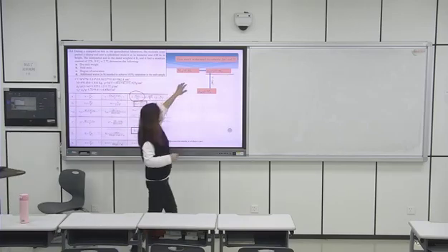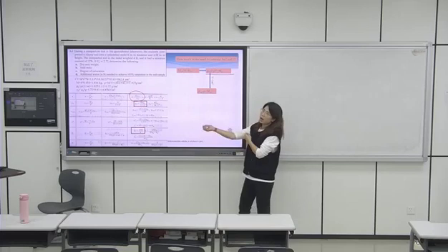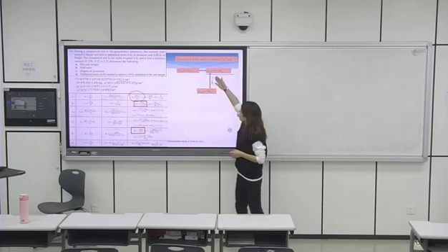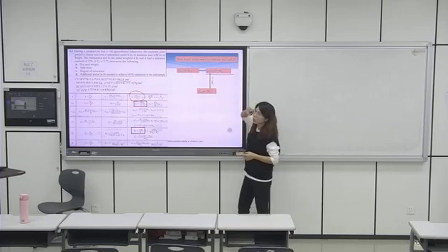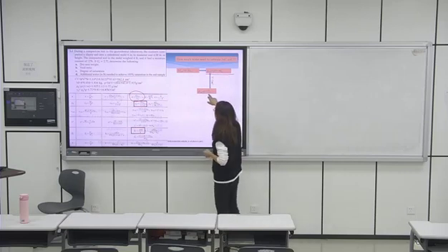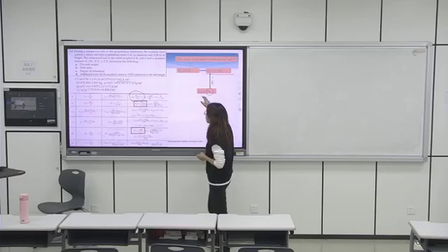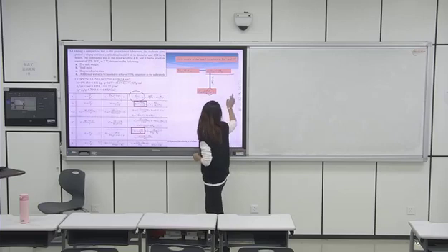From here to here, that is because mass equals density multiplied by volume, right? And from here to here, that is because volume now is 1 cubic meter. And then actually the Mw we need to saturate 1 cubic meter of soil is the difference between saturated density and moisture density.